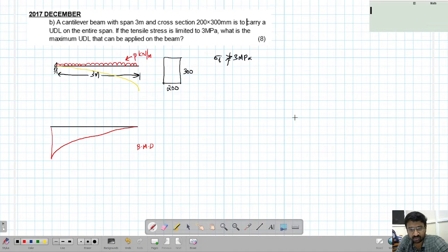Okay. So let's draw the cantilever. Let's say this is the support. This support I can replace with reactions. For a fixed support, there are 3 types of reactions that are possible. There is a vertical reaction possible. If I call this end A, I'll call this vertical reaction at A. A horizontal reaction is also possible.